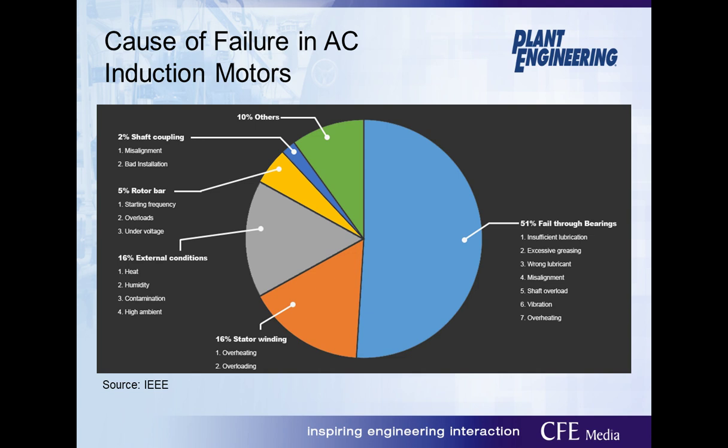If you do not take anything else from this presentation, at least my portion of the presentation, please take this: heat kills motors. Overheating will lead to premature motor failure. It may not be today, it may not be tomorrow, it may not be in a year, but it's eventually going to lead to premature failure. It is also very important to understand your application to avoid overloading. Overloading for increased periods of time will, of course, lead to overheating.